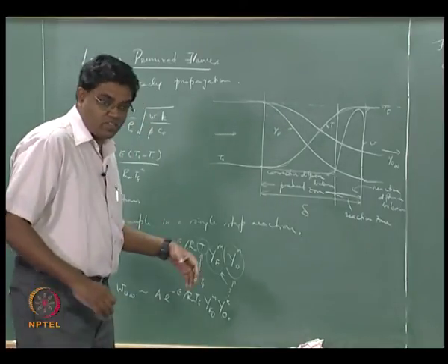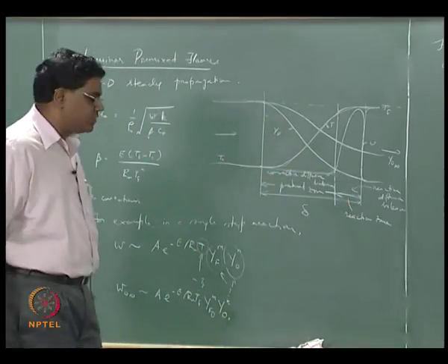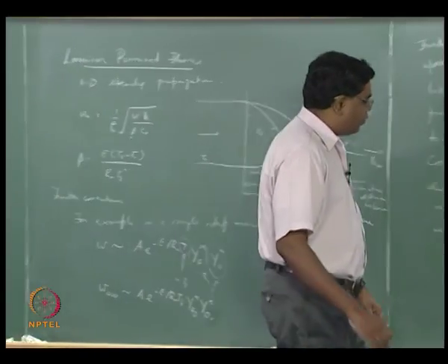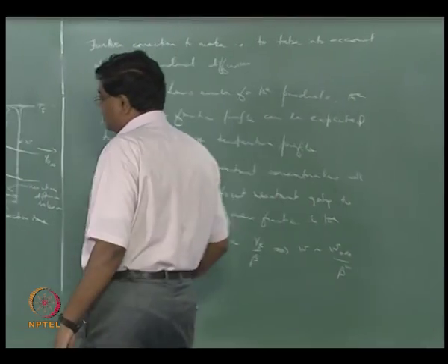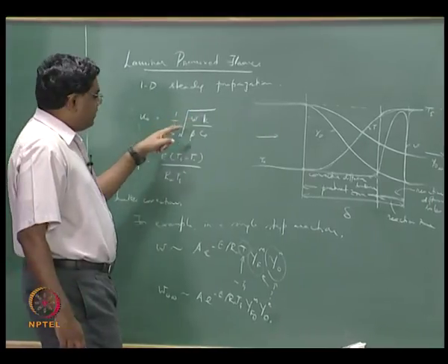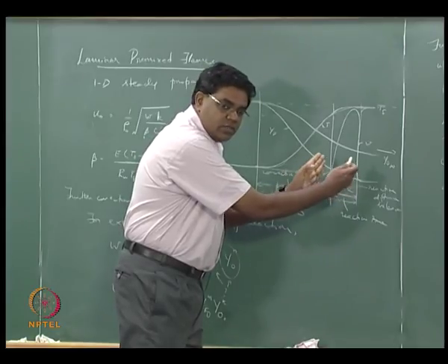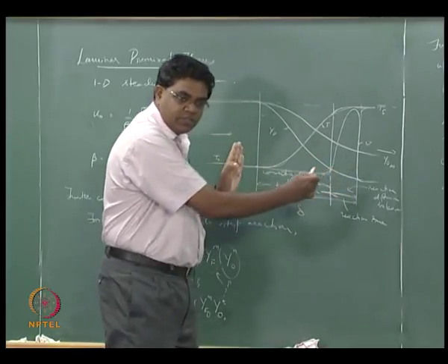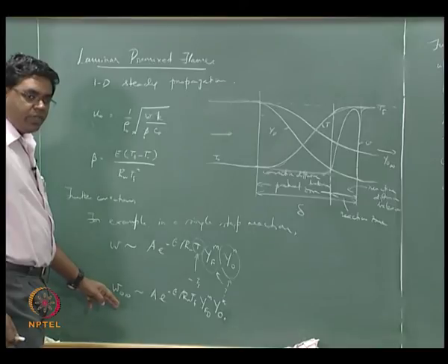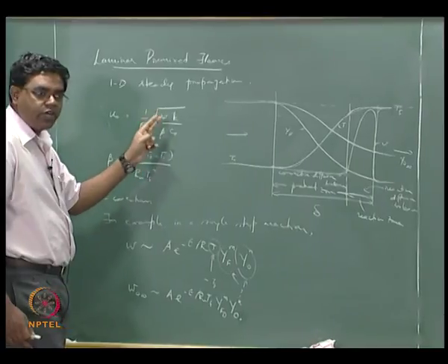On the other hand, if you're thinking about a stoichiometric mixture, then both of them are going to be equally deficient, so you have to make this correction, so keep that in mind. That's an additional correction that we want to do. We want to go back and say this W is not going to be just W naught infinity. This beta here was to make sure that this W, whatever it is, W naught infinity or not, is going to be confined to a small region when compared to the flame thickness. But on top of it, if you now say W is actually W naught infinity, then that correction says no, it is W naught infinity divided by beta power m, that's what you have to plug in there.